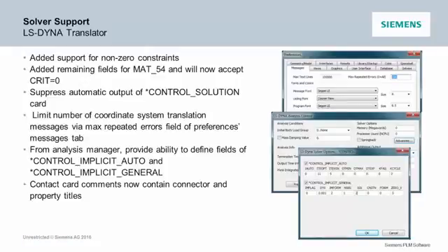Again, this is actually kind of launch control and setting up the jobs and getting them running, and then we continue to add material property support. We've also added a user-defined material for DYNA where you can set up any DYNA material. You just tell it what the keywords are, what values you want. So now you can actually handle any DYNA material. You can kind of code it up yourself.